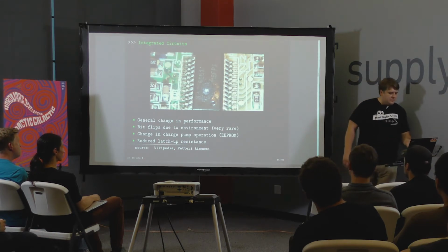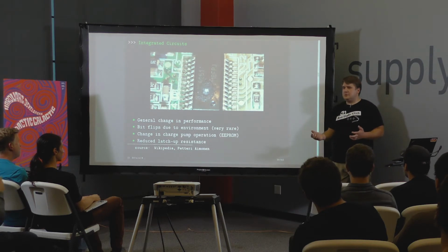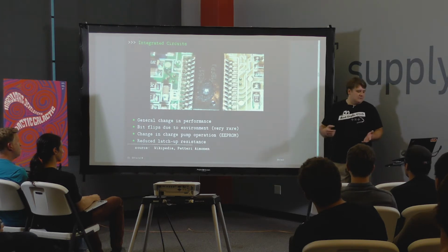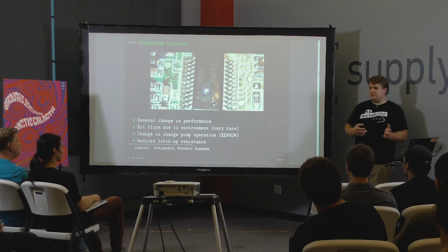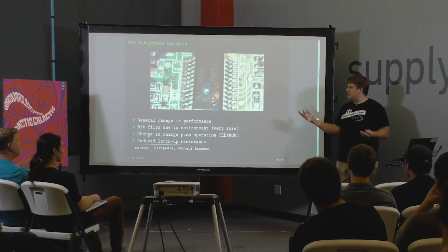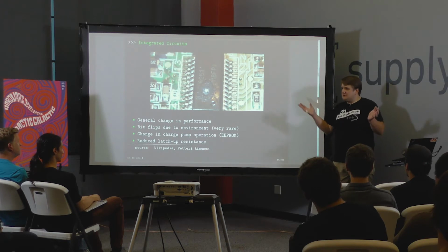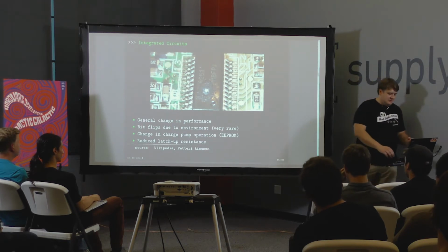And one of the really weird things that I've seen happen is that when you create semiconductors that are CMOS, you can create a parasitic bipolar junction transistor inside the CMOS, and it can create a regenerative effect that will eventually toast your stuff. That's called latch up, and there are different ways you avoid latch up. I've seen a chip actually fry because it seems like we've undone the mitigations that they put in for latch up. So even that gets weird.